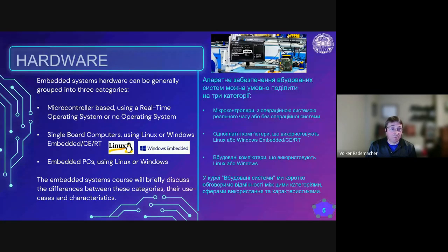1,000,000 times a month. And this cannot be running on Windows or Linux even, because 99.9999% of the time, Linux might meet the timing requirements, but the one time that it doesn't might destroy the engine. So when I'm talking about a real-time capable, it has nothing to do with a real-time clock. It has everything to do with responding to external events within a definable time frame.